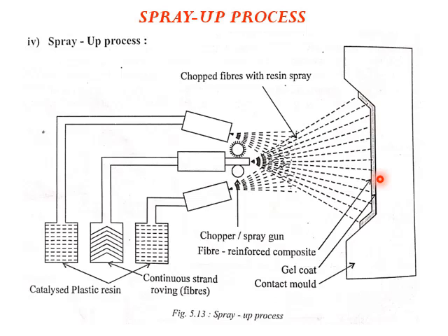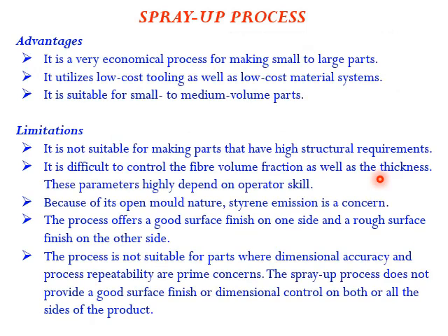This is an improved version, where we can control the amount of resin and the amount of discontinuous fibers which you are going to spray against the walls. Now, what are the advantages? It is a very economical process for making small or large parts. It utilizes low cost tooling as well as low cost material. It is suitable for small to medium volume parts.